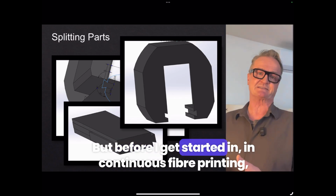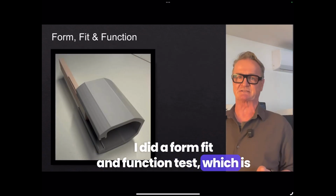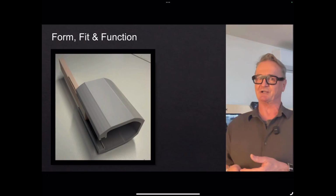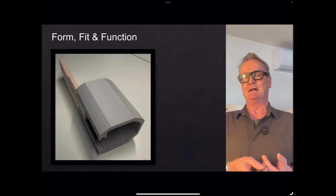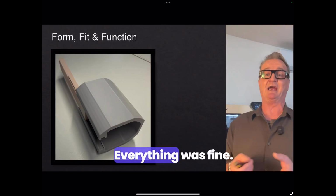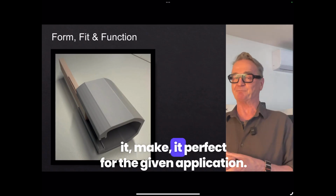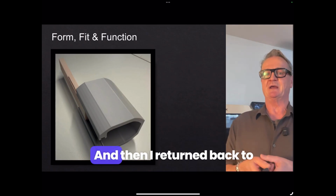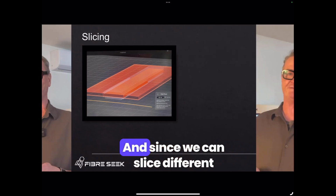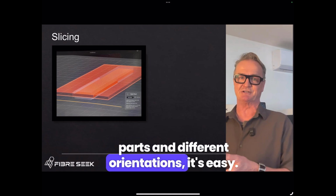Before I got started with continuous fiber printing, I did a form, fit and function test, which is just a simple PLA print, just to look: does it work? Is it easy to assemble? I also brought it back to my home and tried it out on the umbrella to see if it works. Everything was fine. I did a few tweaks to make it perfect for the given application. Then I returned to the office and started slicing it. And since we can slice different parts in different orientations, it's easy.